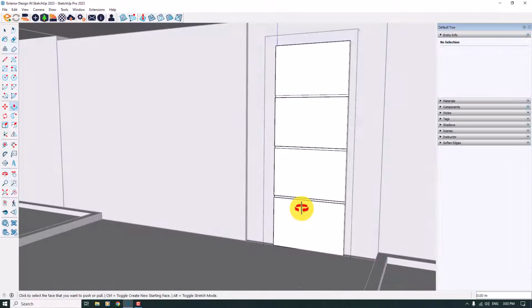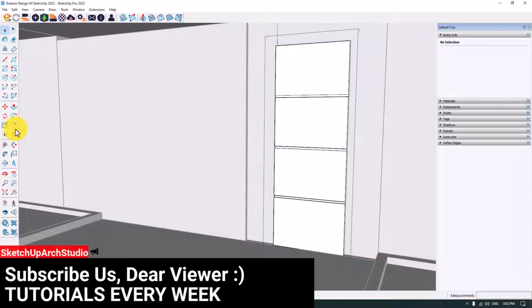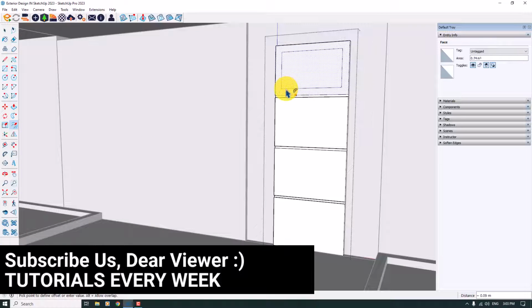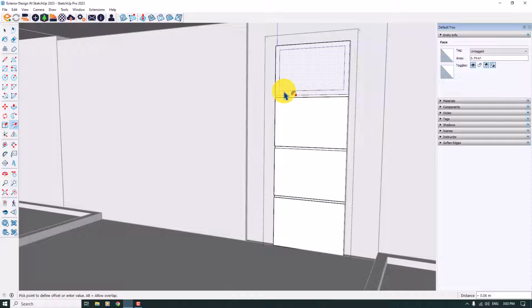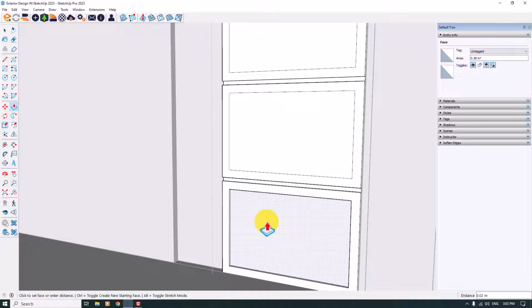And some detail like that can really make your renders, your doors, your windows, and all of your architecture elements much more realistic. So pay attention to these type of points. It takes a little bit of time, but be patient because the result is really good. In the offset job, I will add another design about, for example, 6 centimeter, like that, and move it to the downside about 1 or 2.